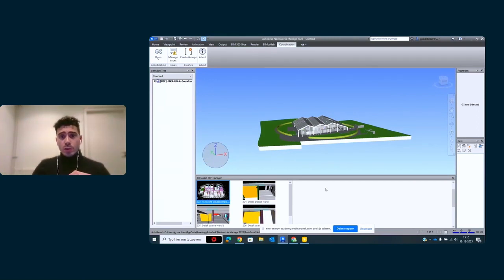So we have the possibility to use two different tools, Navisworks and Solibri, and we use Navisworks to make the clash definitions, and depending on how many clashes, we connect the clashes to BIM Collab.